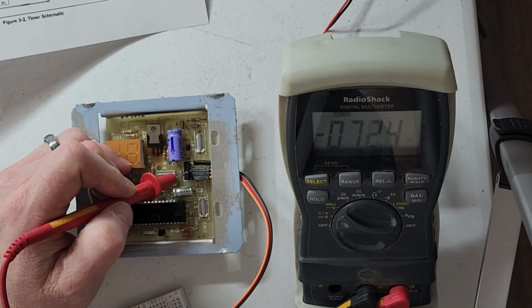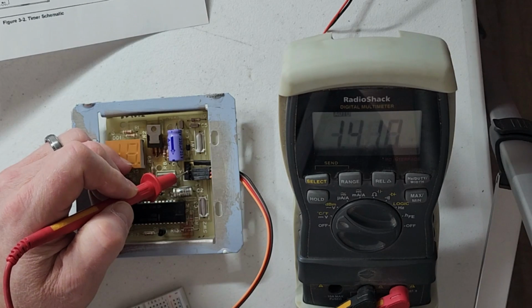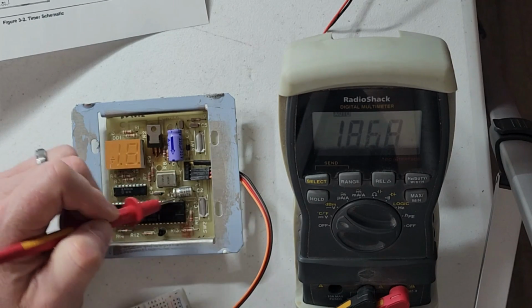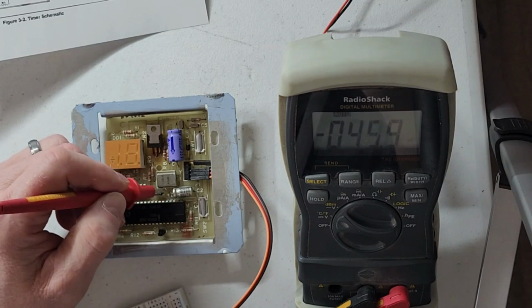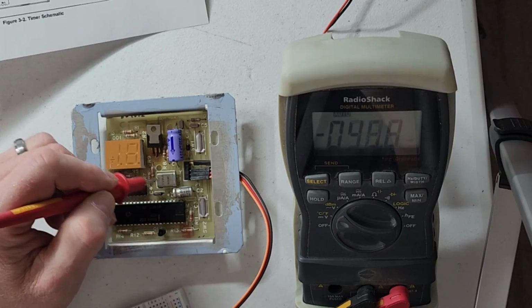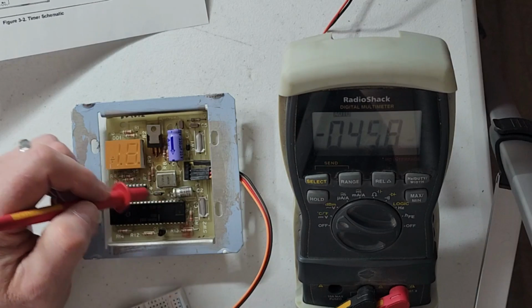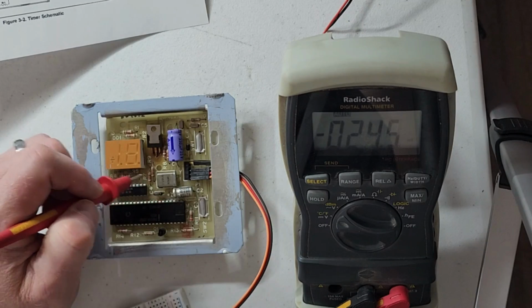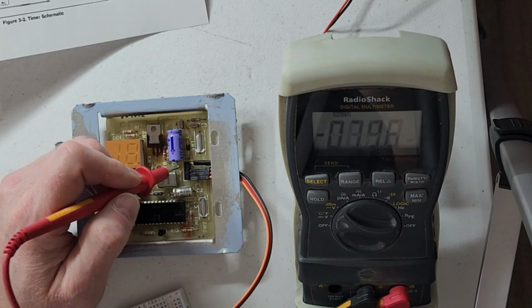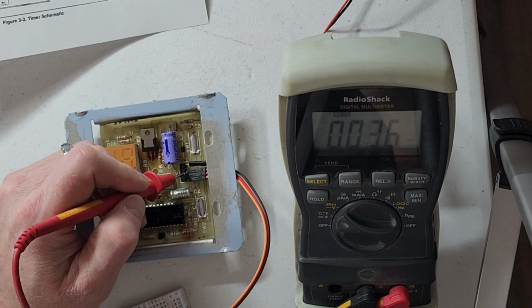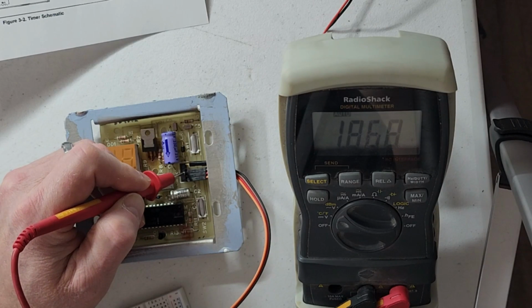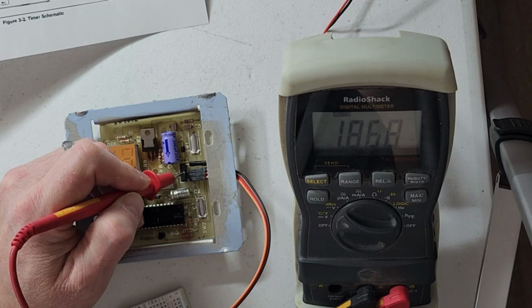Right, but right now it's at 1.8 volts. I'm assuming it's not floating. I'm assuming there's a resistor to power somewhere, like a voltage divider or something, that's causing it to have 1.8 volts until you short it to ground.